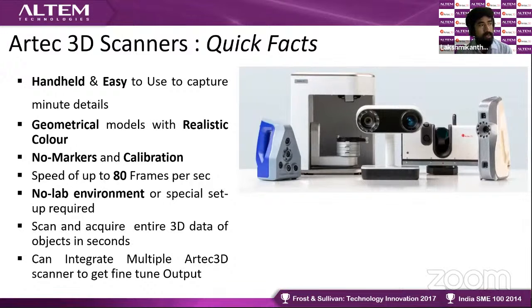And within a very short time, as well as in a much more broadened way. After 3D scanning is done, the next step, if it is reverse engineering or you want CAD-oriented models, is that we go through a process of reverse engineering, where we convert each and every dimension and constrain the sketches. That is for parametric modeling, which is a manufacturing level of design.